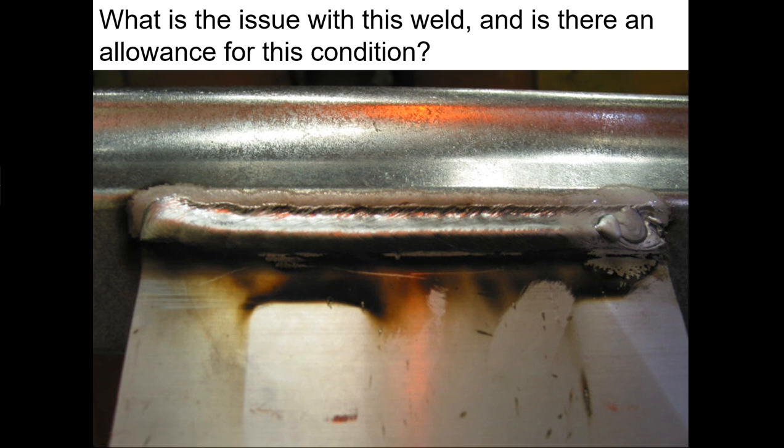Now, you have to look at your own specification when it comes to this one. However, there should be no undercut in the first 10 millimeters, last 10 millimeters. You should not see any undercut here or here. Now, no matter what the specs say, and the specs are very clear that there is something allowed, rarely do you see anything more than 25%.